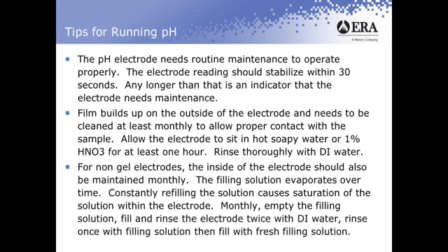So for those of you who are using the non-gel electrodes, and those are the electrodes where you have filling solution inside of them, the inside of that electrode should also be maintained, and I would recommend on a monthly basis. What happens over time when you're using the electrode is that you're going to pull that little rubber stopper out of the hole on the side, and the filling solution in there, the water in it, is going to start evaporating over time.